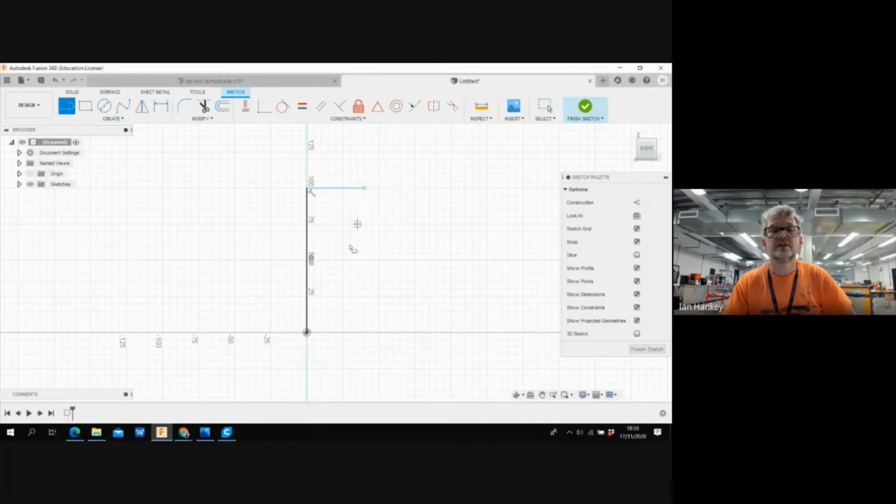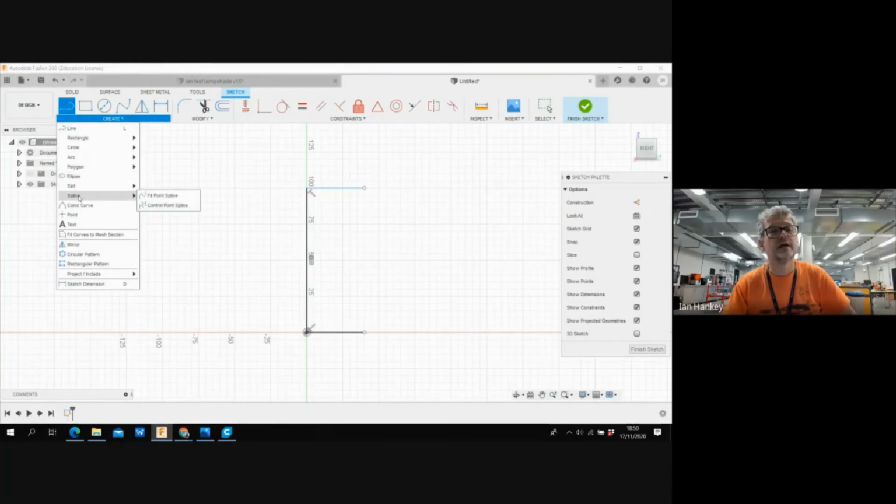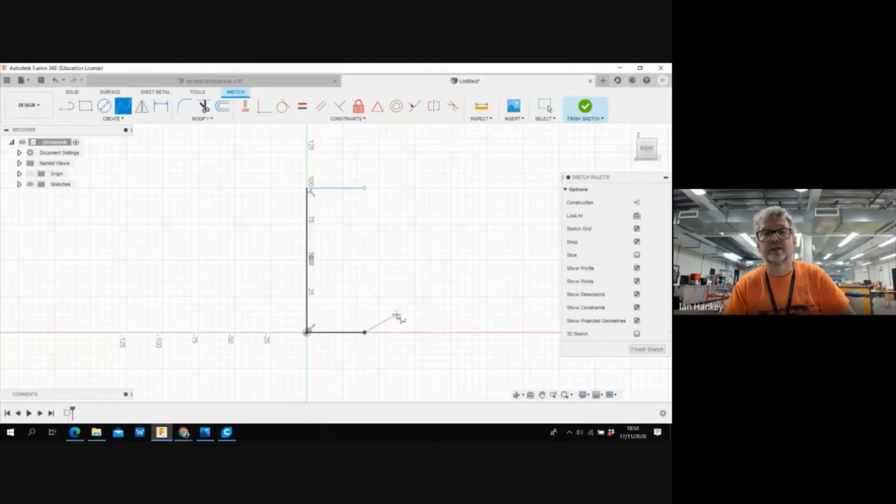And I'm going to finish that sketch there, and I'm going to go down to the bottom, and I'm going to go out again, 40, left click, and click OK. Now again, I'm going to go for a slightly different kind of line now. I'm going to go for spline. This is a curve, basically. Every time I actually click a point here, I should get another curve, and I can click that. I'm not very happy with that. It looks a little bit.